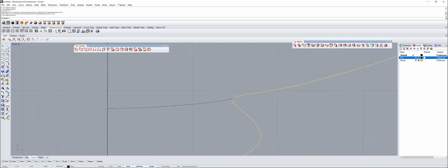So I'm going to type the Split command without selecting this one, only this one. Write that on your paper that you're going to stick to your wall. It's asking me what the cut object is, so this one is my current object. I click on it, and enter, and now this part is a two-segment curve, one and two. There it goes, guys.